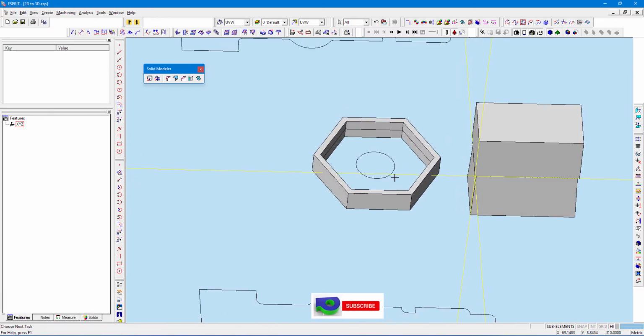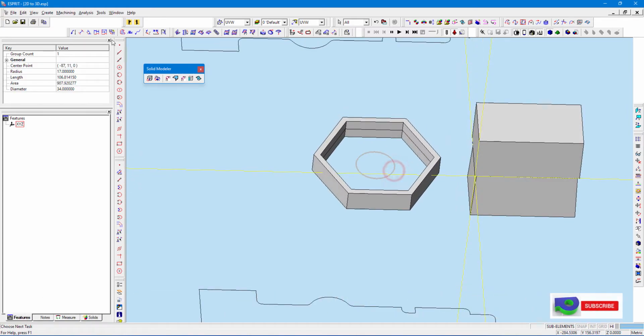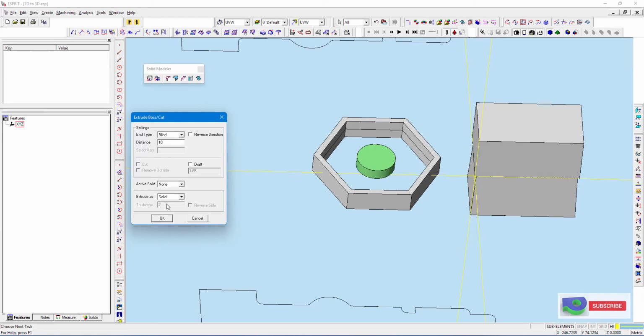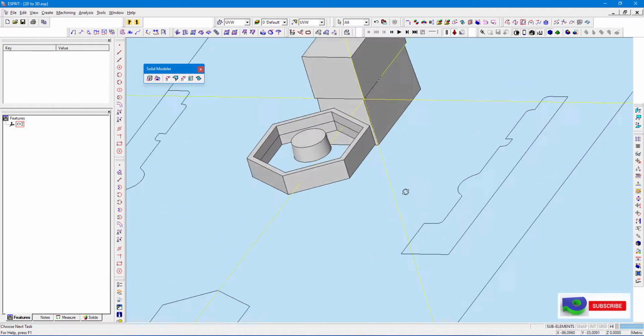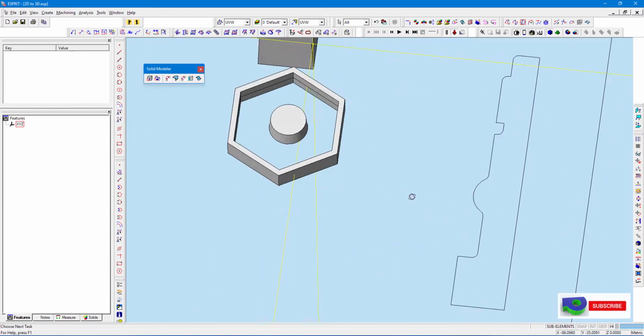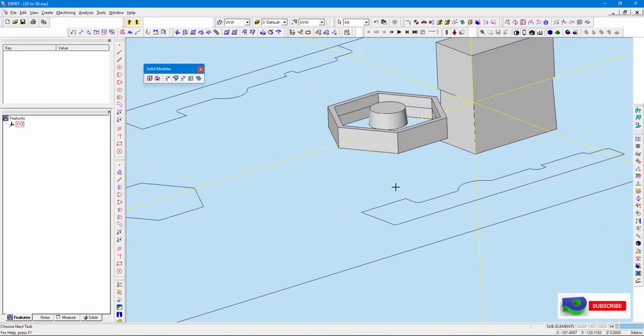And if you want to convert this sketch to be generated for extrusion, I will just select extrude, and it will be like this. And if you want a draft, you can give a draft to identify it easily. I will give 15 mm and click OK. And see here, the draft has been created, the sketch has been created, and the 3D model is created.